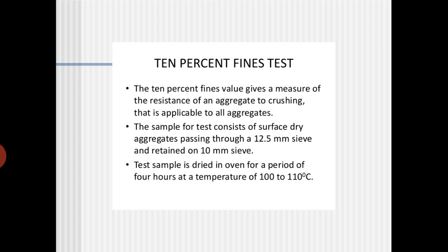10% fines is equal to the weight of the 10% fine particles divided by the total weight of the aggregate, that can be calculated. I'll repeat it one more time. 10% fines is equal to the weight of the fine particles after applying the compressive load, to the weight of the aggregates.